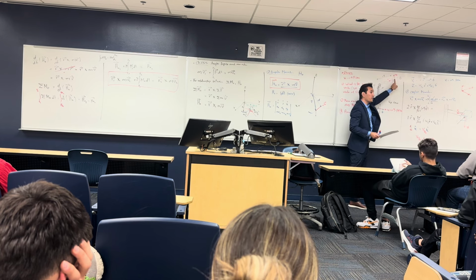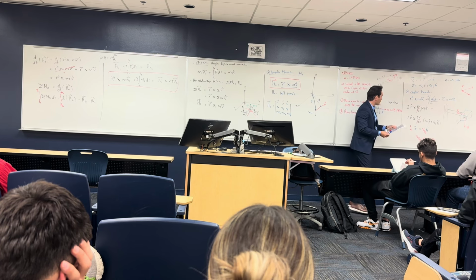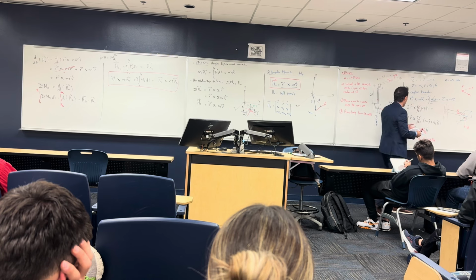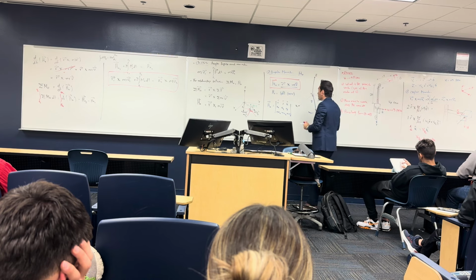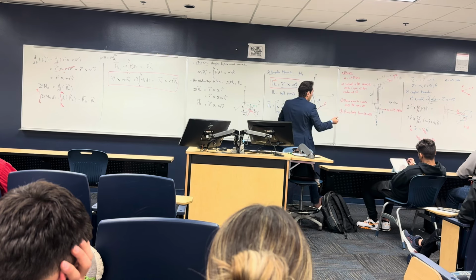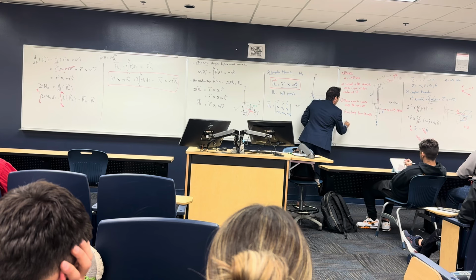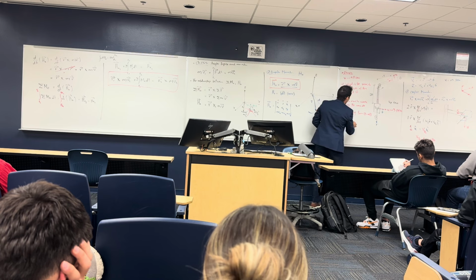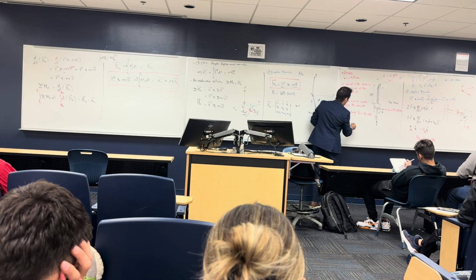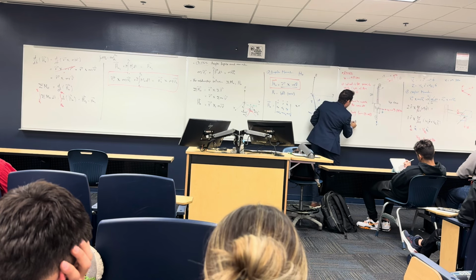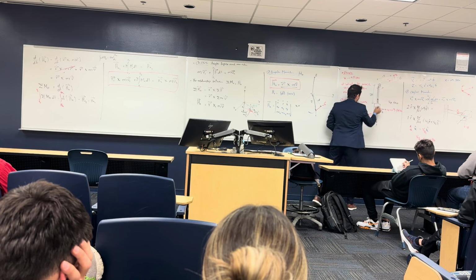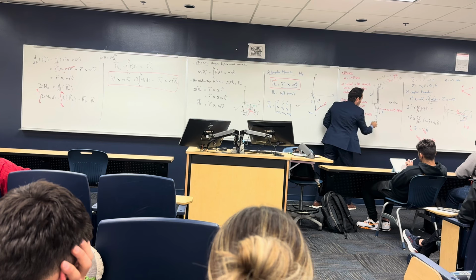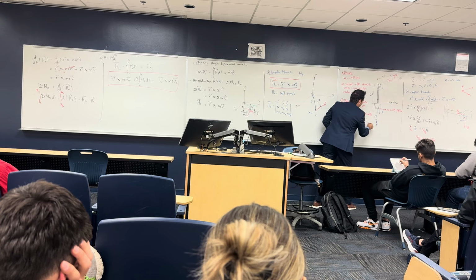So when it gets to position 2, it's still constant. So VR2 is going to be equal to 0.4. So this will give us that V2 vector has an R component of 0.4, and it's negative because the arm is going this way, in the direction of R hat, plus 1 in the theta hat direction.